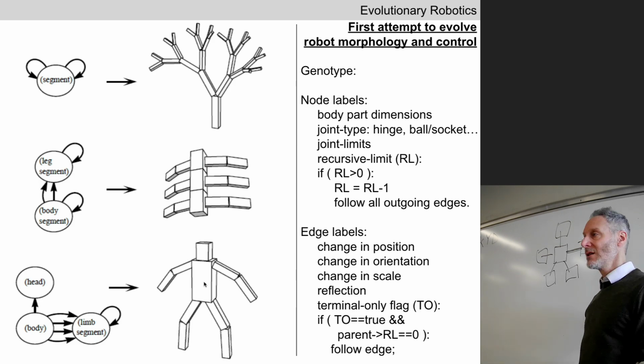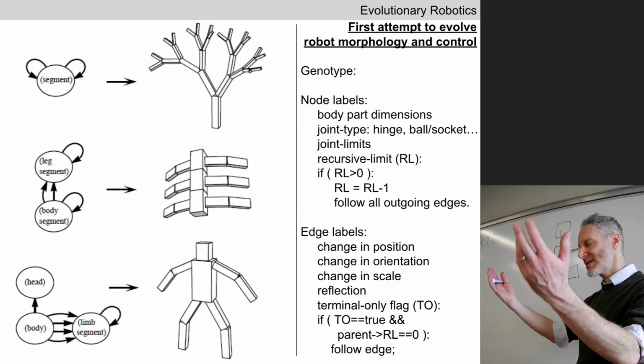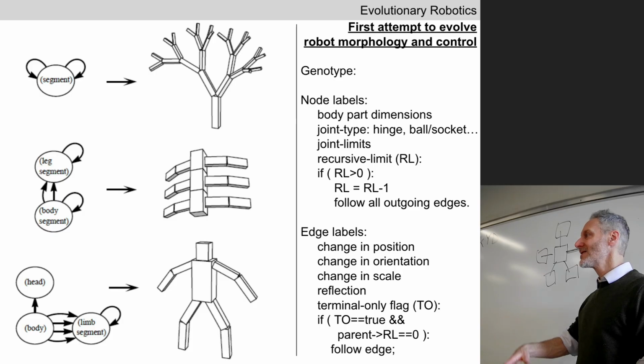We could then put this phenotype, this robot, inside a physics engine and see how well it does at swimming or walking or competing for the cube, whatever it is, and assign a fitness value to it. We go on to the next graph in the population, evaluate the resulting phenotype, and keep going until we evaluate all 300 virtual robots, exactly like you're doing in your final project. Delete the ones that get low fitness at swimming or walking or competing over the cube, and make randomly modified copies of the surviving genotypes.